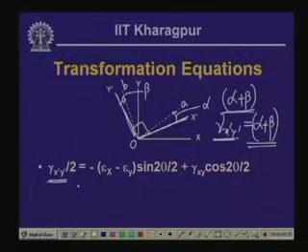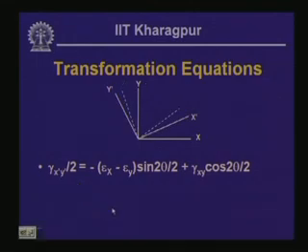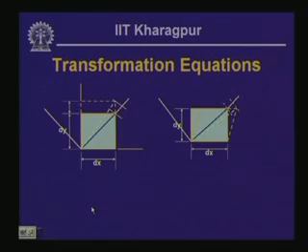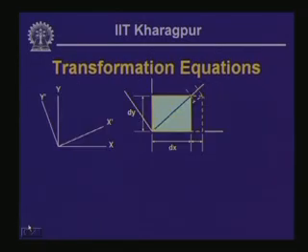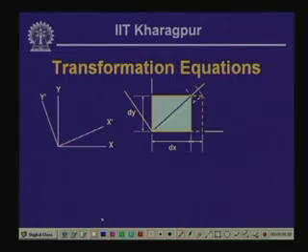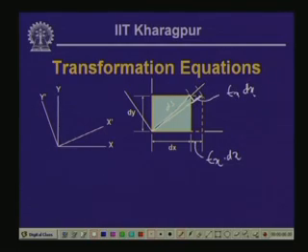Now, to compute those angles, let us go back to the earlier one. In this particular case where we had computed the deformation of the diagonal which was originally ds, and finally it came to this particular position, we have already seen that this particular extension is epsilon x dx, and this particular stretching of the diagonal was epsilon x dx cos theta.